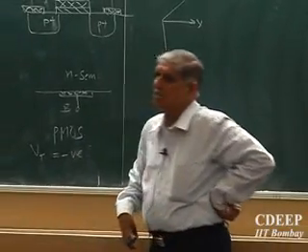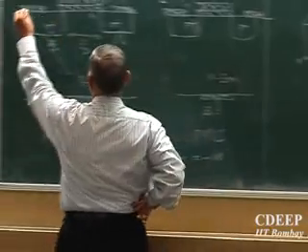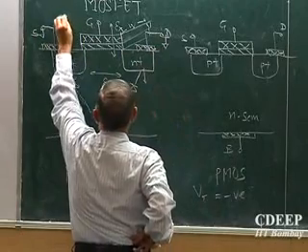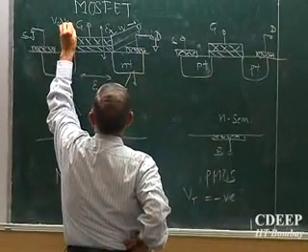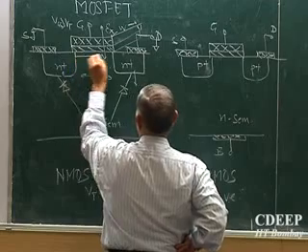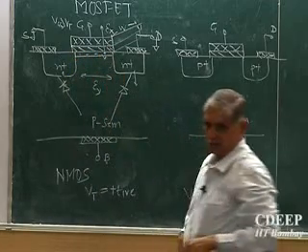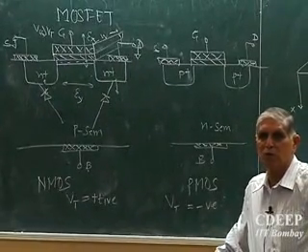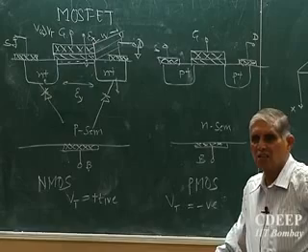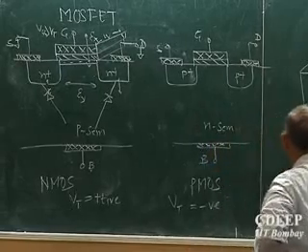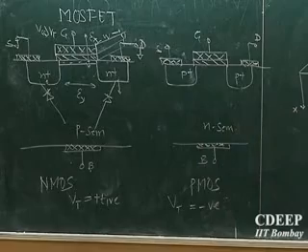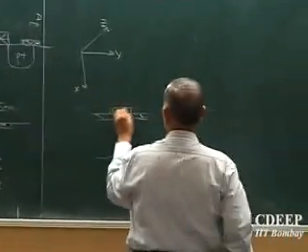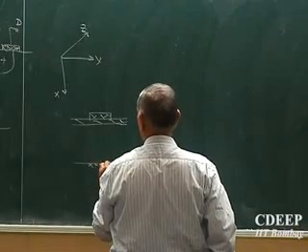Now in the case of MOS capacitor, we said that if I apply plus VGS, and I ground both of them, and I say apply VGS greater than VT, then I figure out an electron channel appears. If VGS is greater than VT, an inversion layer appears completely from source to drain. Is that clear? Now the catch there is, in the normal MOS capacitor, this is oxide or insulator and this is your metal plate. This is also your metal plate.